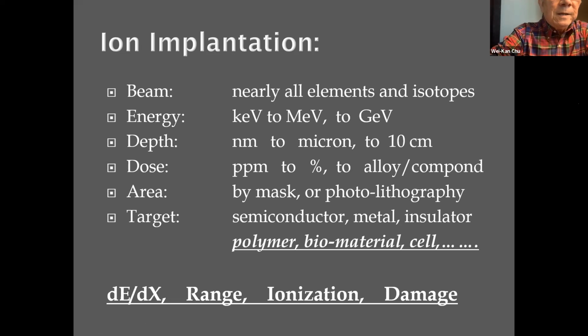Very good question. Let me digress into a different area. For example, I want to make an n-type dopant. In order to do that, I need a phosphorus implantation. When I do the phosphorus implantation, the beam current is on, and the phosphorus goes through a window.